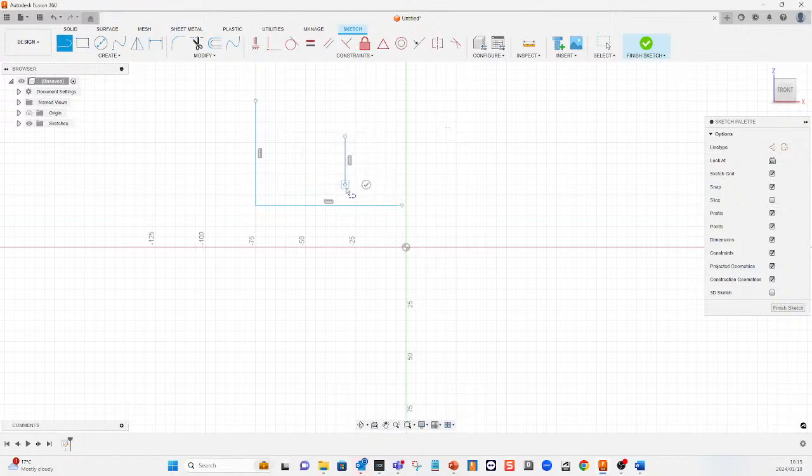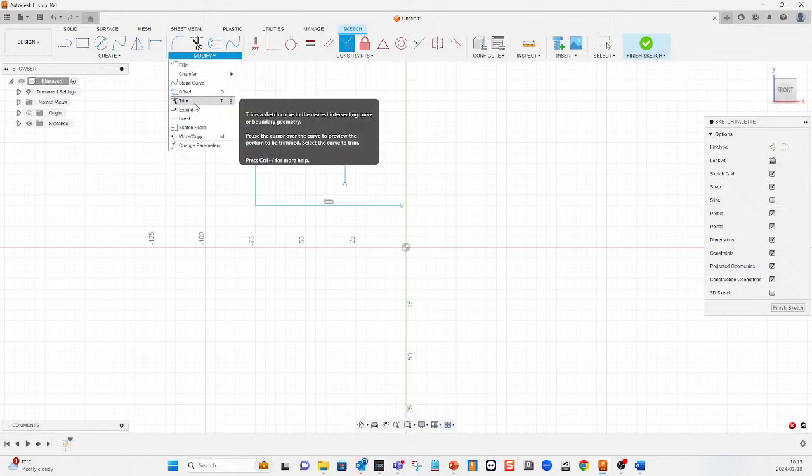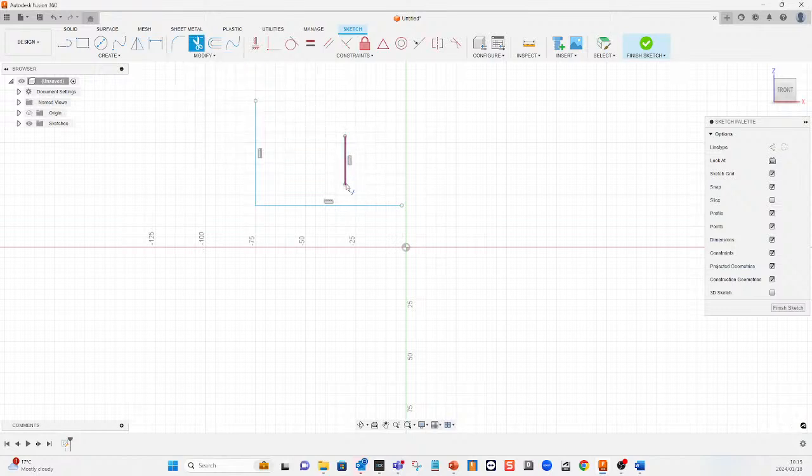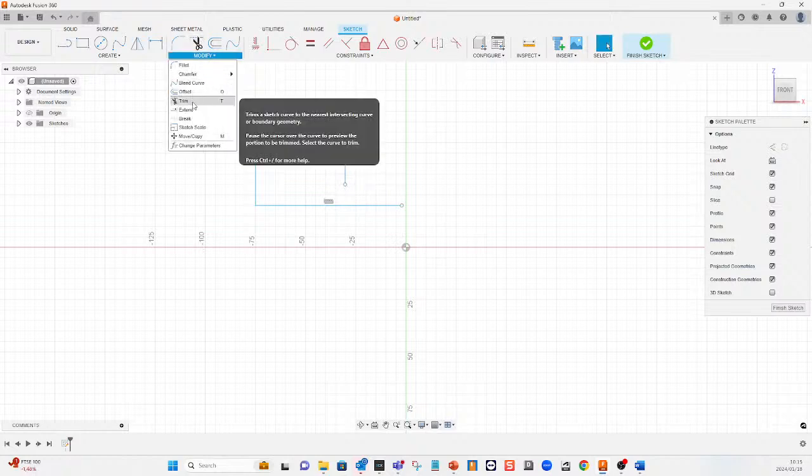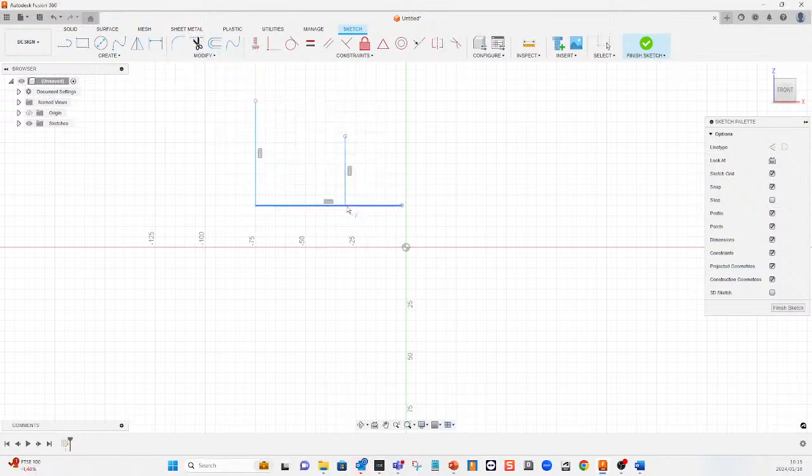If you've got another line, you can also use the perpendicular. What does the perpendicular do? Constrains two objects so that they lie perpendicular at a 90-degree angle. Just selecting that and the line, you'll see sketch geometry is over constrained. That error will occur because this is already creating a 90-degree corner. If I'm just going to create extend, you'll notice it's already at a 90-degree angle.